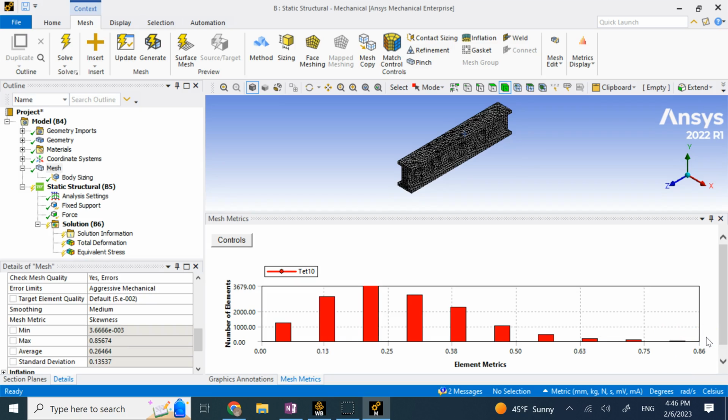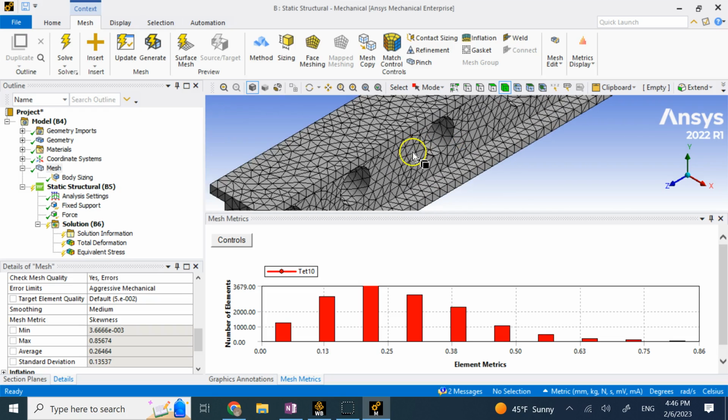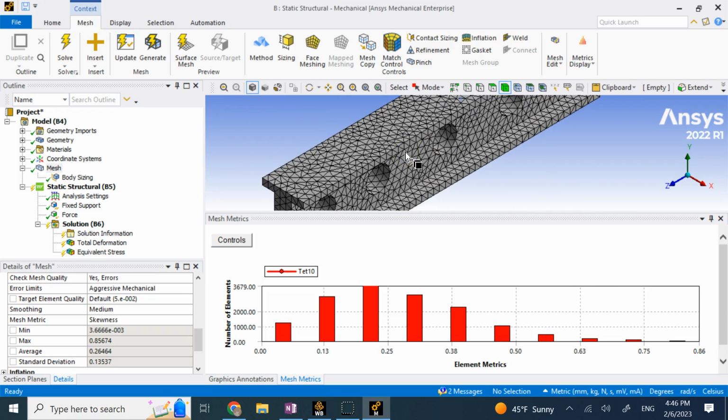So you clearly see that reducing the mesh size would increase the quality of the mesh, of course, because now I can cover all of the areas with finer meshes, and I can approximate the geometry way better without the need to distort the shape of my tetrahedrons here.